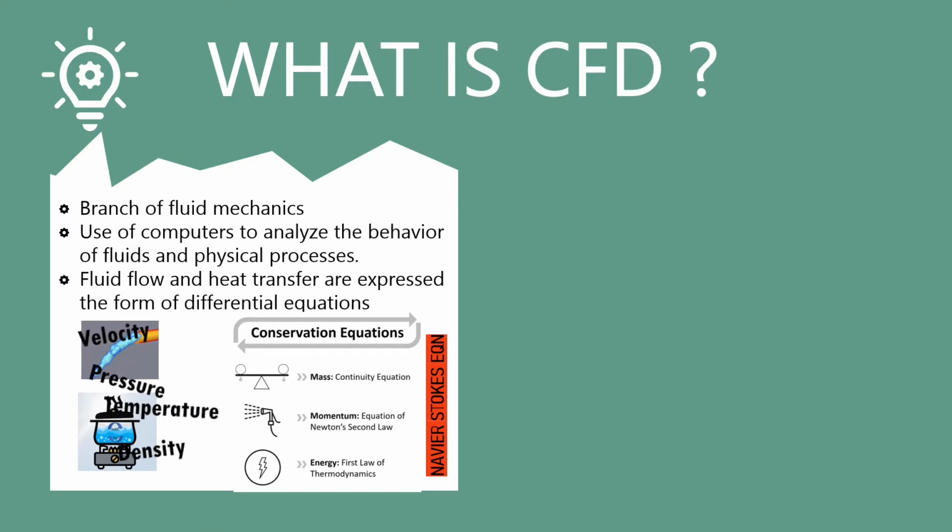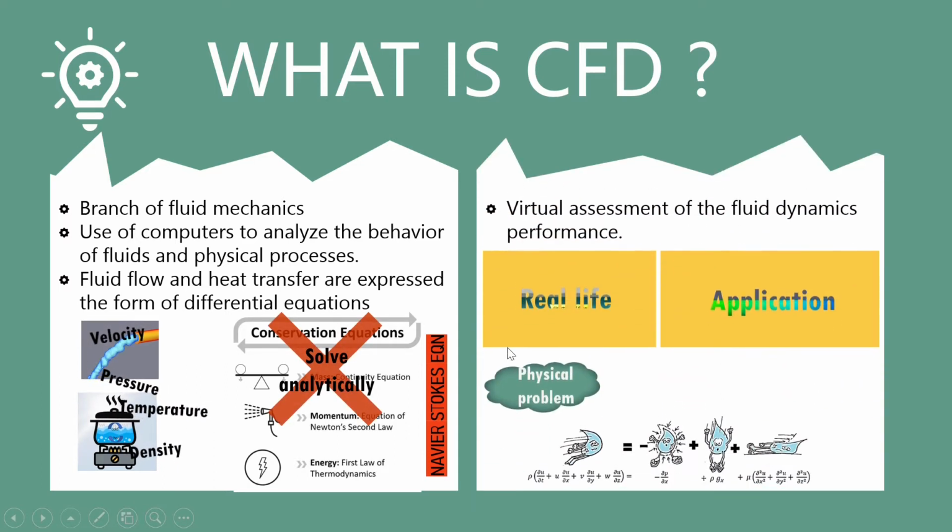flow process. The Navier-Stokes equations are the broadly applied mathematical model to examine changes in these properties during fluid flow and thermal interactions. The Navier-Stokes equations are derived from the conservation laws of mass, momentum, and energy, which are in the form of partial differential equations and cannot be solved analytically. CFD solvers transform these laws into algebraic equations and are able to efficiently solve these equations numerically.